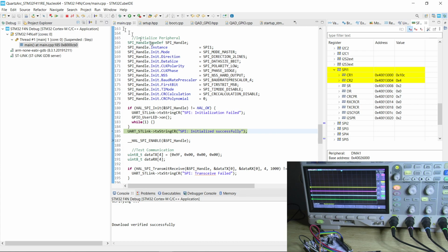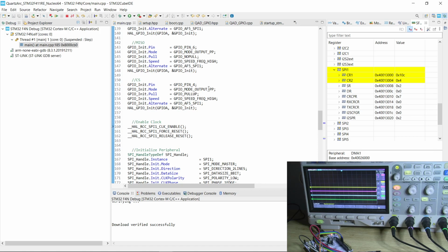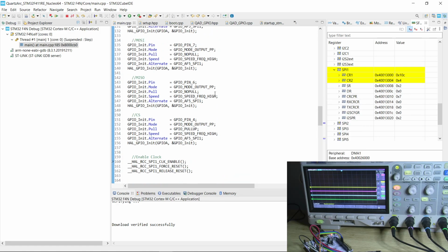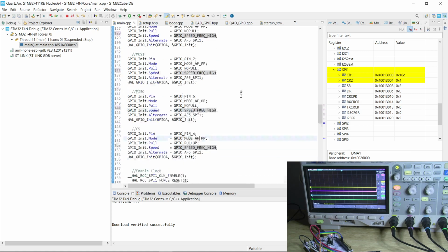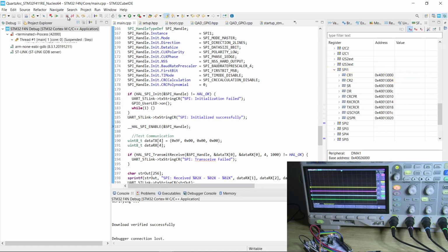And we can see on the scope, even at this point, our clock chip select pin is sitting low, which it shouldn't be. Now, you guys are probably screaming at the screen because some clown hasn't actually set the pins up in the correct mode. So these should all be alternate function push-pull. My apologies for that. Explains why we were getting some weird behavior.